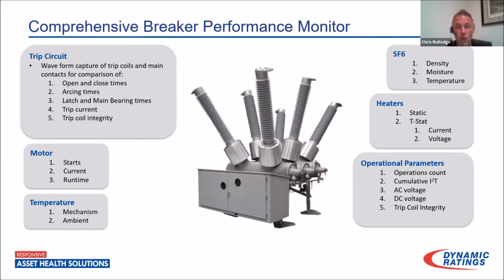As it begins to warm up during the day, some of that hydraulic fluid will be pumped over into a reservoir, and then at night again we'll have a motor run to pump it up as things cool off. So these runs that aren't associated with operations are common with these breakers. The thing we don't know is what's normal.